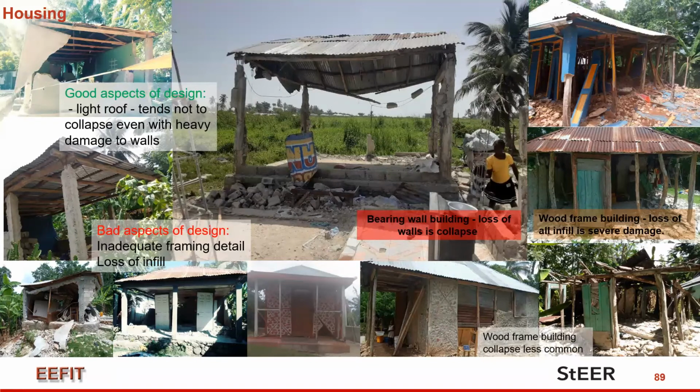An advantage of small stone infill without heavy plaster is that it will possibly cause less injury when it falls as small pieces. Plastered block infill might more likely fall as one wall, and bracing systems seem to have less severe damage, especially if bracing is used for all panels. Next, please.